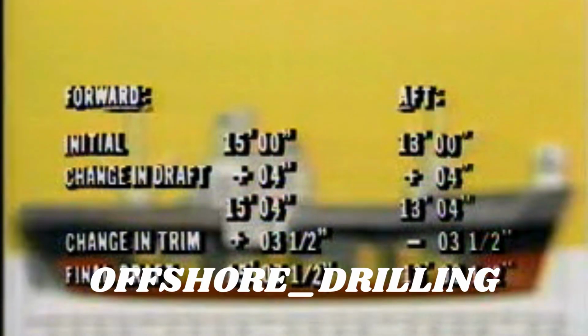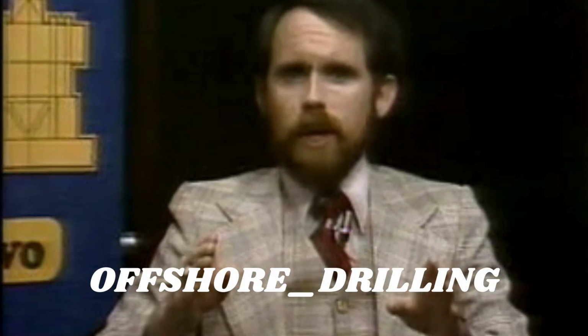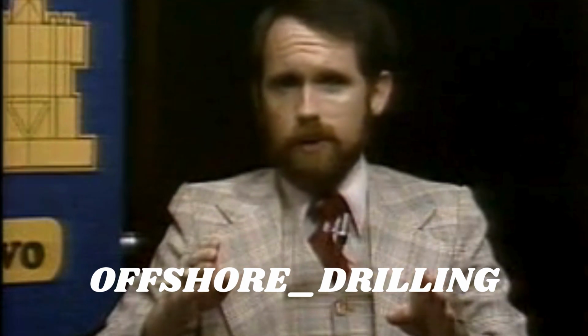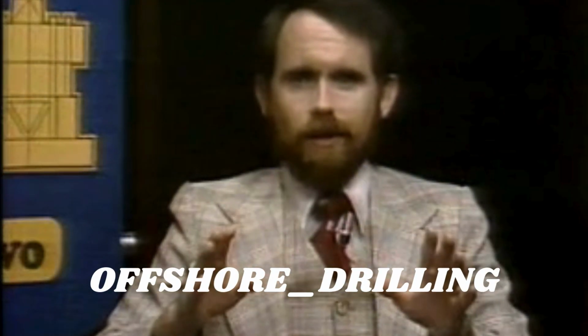The aft draft started at 13 feet and increased 4 inches due to added cargo, and decreased 3.5 inches due to change in trim, for a final draft of 13 feet and 1/2 inch. The mean of these two final drafts is 14 feet 4 inches, which agrees with our earlier finding for final mean draft and is a good check.